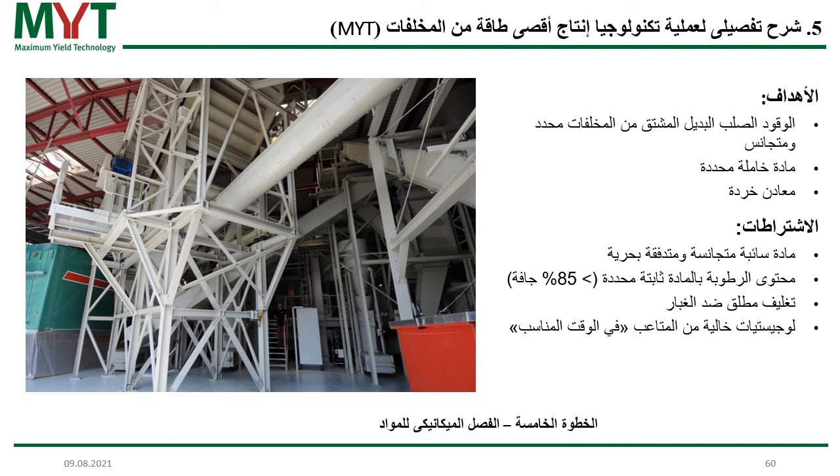Of course, as a prerequisite, you need a loose and homogeneous and free-flowing material. You need a specified consistent moisture content. You need absolute dust-proof encapsulation because when the waste is so dry, you have a lot of dust all around. And you need trouble-free, just-in-time logistics. So as soon as a container is full with RDF, it has to be dispatched. But this is not so difficult to handle if you have the right concept. And of course, we can assist you with the right one.